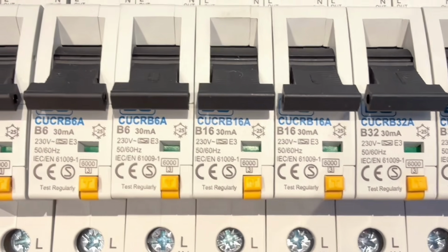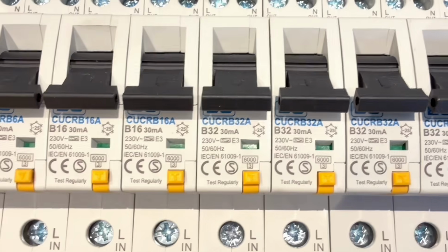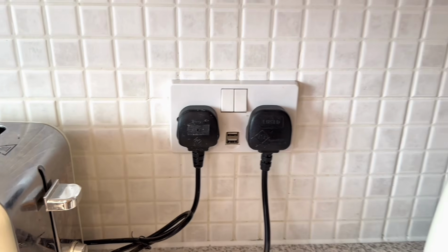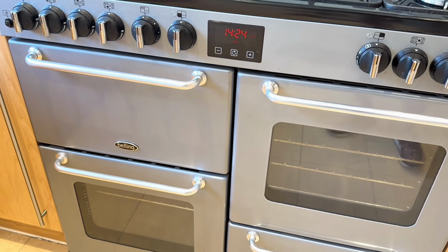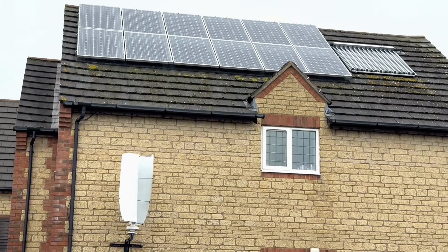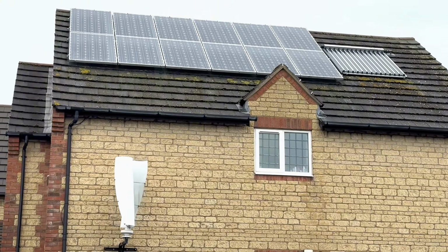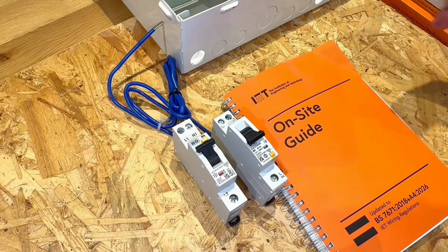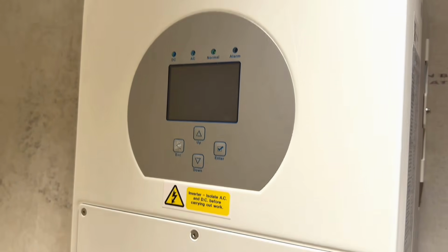Circuit protection is evolving over time, and it's incredibly important now to understand whether our devices are uni or bi-directional. Let's go back and think about a standard consumer unit. We're so used to the electricity going out from the consumer unit and feeding things such as our sockets and our cooker. However, with microgeneration in the form of solar and micro wind, all of a sudden some of our circuits actually send electricity back into our consumer unit and feed the other circuits within the installation, or possibly export that electricity. Those devices being fed in from that inverter need to be bi-directional.